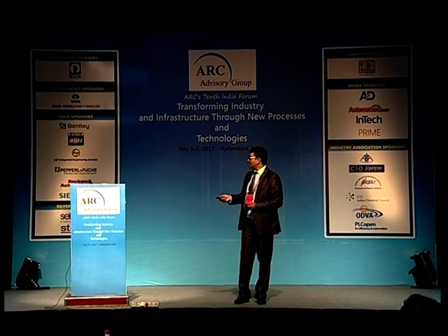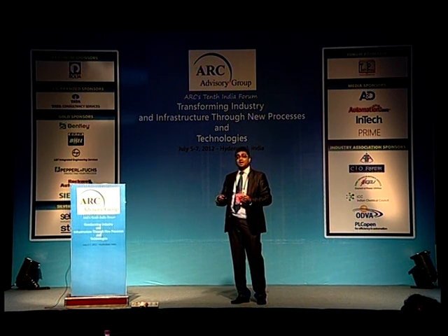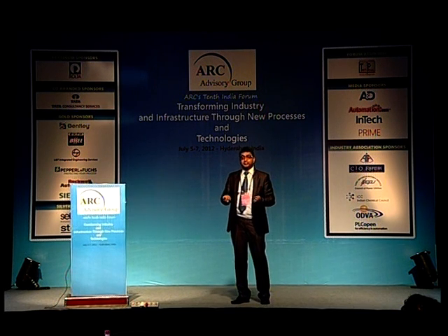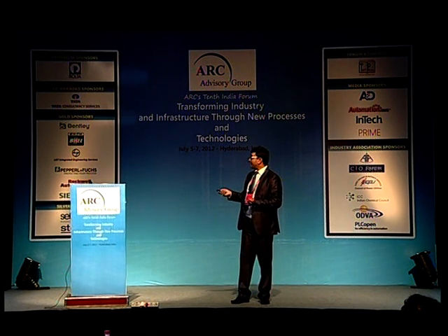In addition to the existing set points, we also provide mill optimization in combination with set point, so that the suitable mill combinations to achieve the heat rate are also provided along with the mill loading.